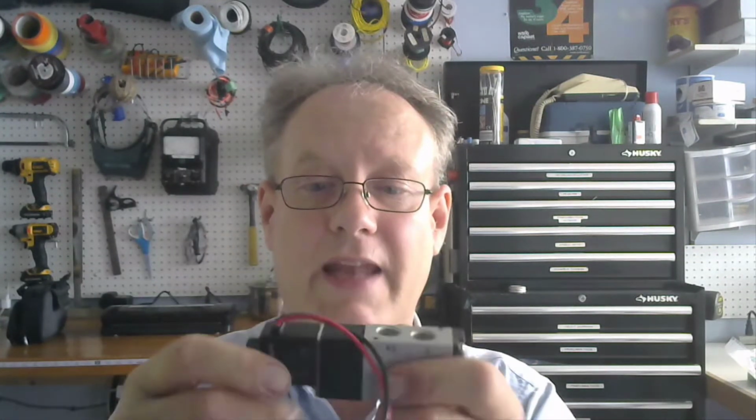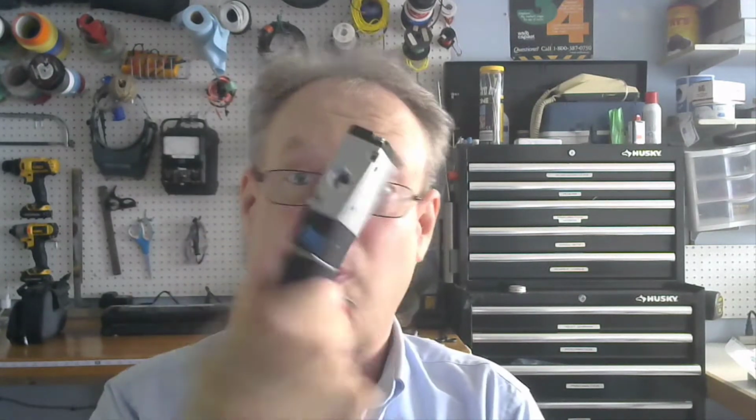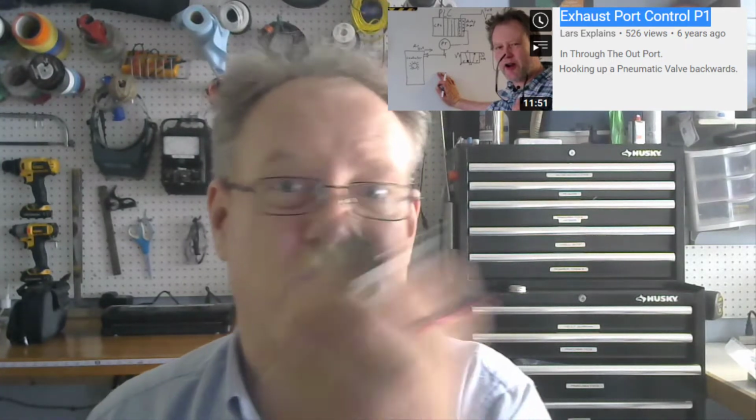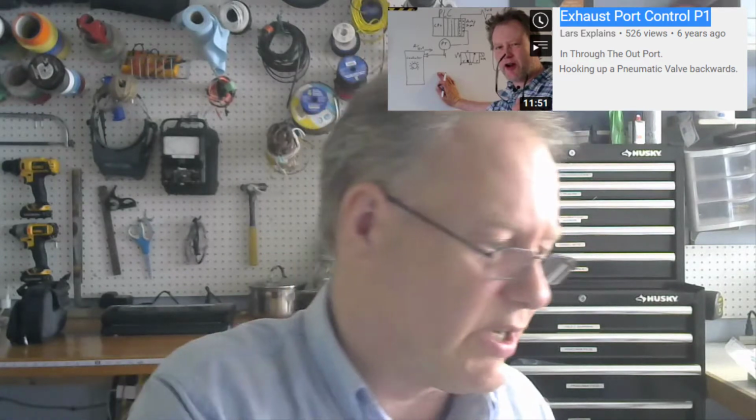Oh, wait. This is a valve. This is a DCV, an electronic DCV, and it's only a one solenoid DCV, so there's a spring in it, and that has a natural state. By the way, that's a 2-3. It's only 3 ports on this. If you want to get into outside the box thinking with this stuff, I did a video with this lab. You can search it on my YouTube channel. It's something about using exhaust backwards, the exhaust port. Type exhaust for searching. That's not ancillary equipment. This is another DCV. It's also not ancillary equipment.